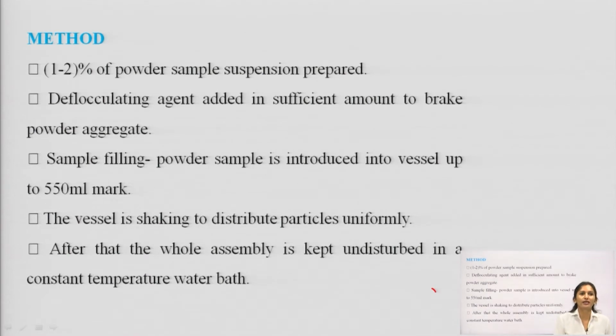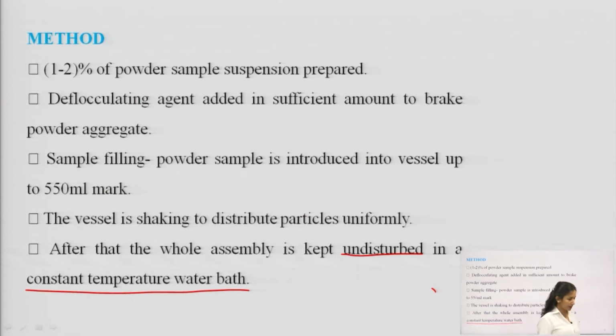After that, the whole assembly is kept undisturbed in a constant temperature water bath. Undisturbed, so that there is a rate of sedimentation without any hindrance. If you come and shake it in between, what will happen? The flow of the particles will not be streamlined. So, you have to keep it undisturbed in a constant temperature water bath, because the rate of sedimentation of the particles depends on the medium viscosity.